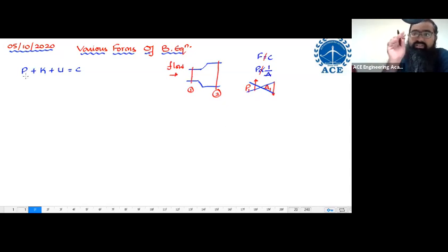Pressure over here is a pushing effect by one section on the other section. How, or by what magnitude, one section is pushing the other section. Please understand, in these cases, always start with the continuity equation. According to the continuity equation, A1 is less. Now, the continuity equation says if A1 is less, automatically the velocity V1 is supposed to be high. Is it not?